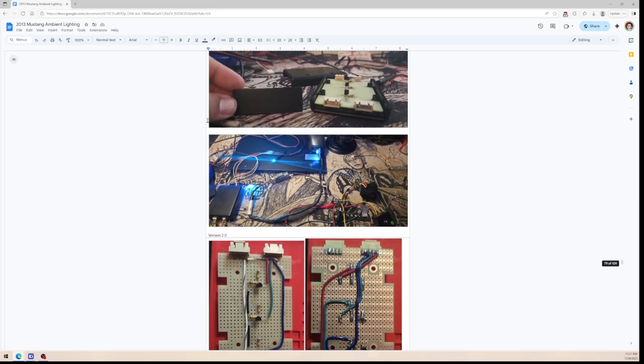If you look here, I did do some testing. So what you see in this photo here is I have a makeshift harness. So here would be my harness from the car, right? An interconnect harness. So this would be what plugs into your door harness. Here you can see it actually plugs into the wire that goes to the map pocket light. So that's the stock LED right there. The wire comes off the side with the RGB signal and goes over here to the 3-pin port.